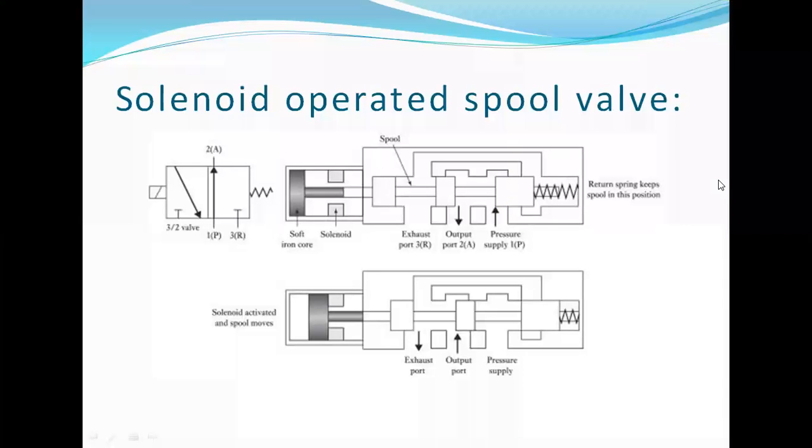And here we'll have a detailed look at the solenoid operated spool valve when it has been connected with respect to our directional control valve. So the directional control valve displayed here, we will have a look. The first one has one square and a second square which is interlinked. The square represents the position, so we have two positions. So the denominator value is 2 positions.